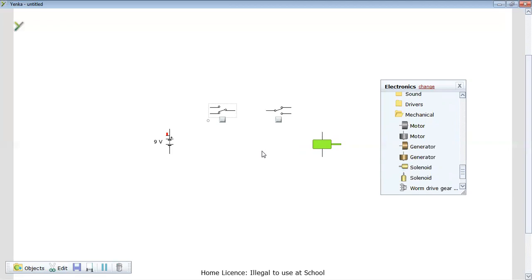So let's start off with the OR circuits, because there's some good little examples I'm going to use here. For that, I'm going to put these this way round, okay? So it goes like so. I'm going to connect my little solenoid, or my cylinder in this case, round like that. The other end of my cylinder around down to the power over there, and that power bit over here. Now, this is the important bit. I'm going to connect that to there and that to there. So this is our OR circuit we're talking about.